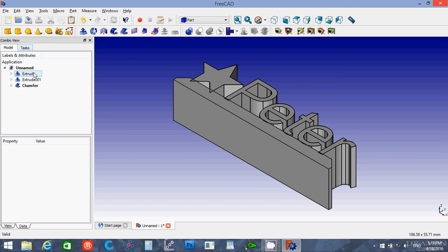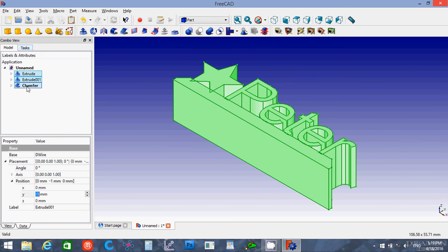But a part that's set up and fused together will always still work on the RepRaps, as long as it's a 3D printable part, but not the other way around. If you do not fuse this when you're designing it in FreeCAD, it will treat every overlap as a difference. It will remove that material. I don't know why, but that is the case.